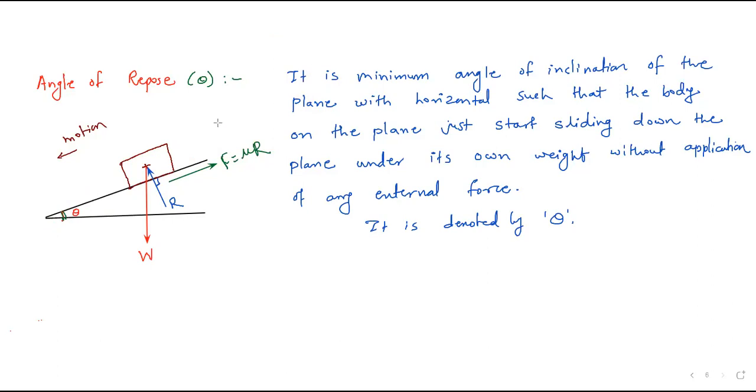So this inclined surface will be your x-axis, and perpendicular to this is your y-axis. So here you can consider your coordinate system like this. This will become your x-axis and this is your y-axis, which is perpendicular to this. Okay, so whatever you apply in summation Fx equal to 0, those forces should be resolved parallel to this plane. That is your summation Fx. And the forces which are perpendicular to this plane, in this direction, that is nothing but your summation Fy.